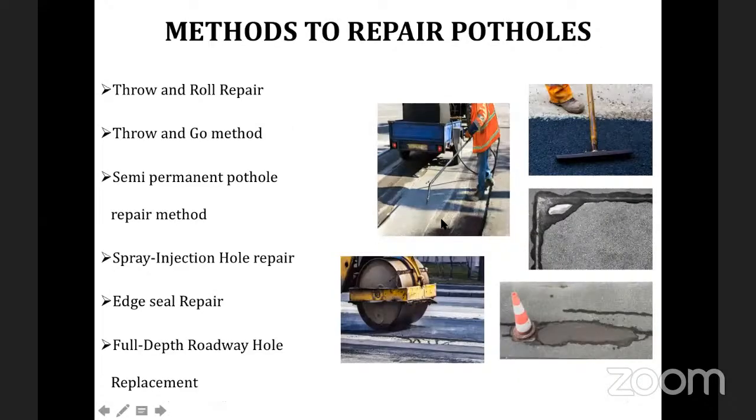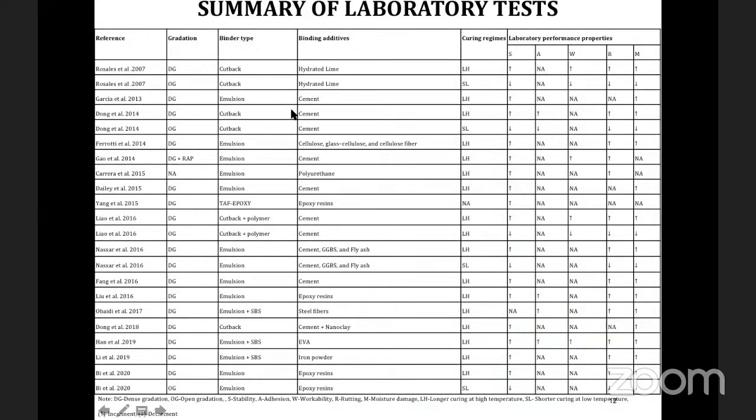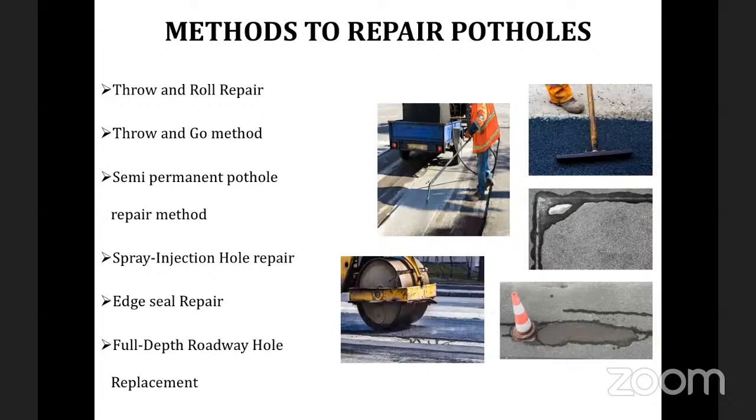Next, once the mix design is done and the mix is made, how will we repair the potholes with these mixes, maybe cold mixes or the ready-made pothole patching mixes? There are a lot of techniques like throw and roll, throw and go, semi-permanent pothole repair method, spray injection repair method, edge seal method, and the last one is full depth roadway hole replacement.